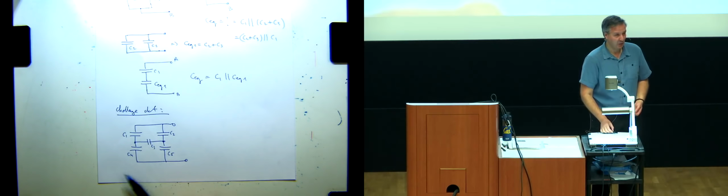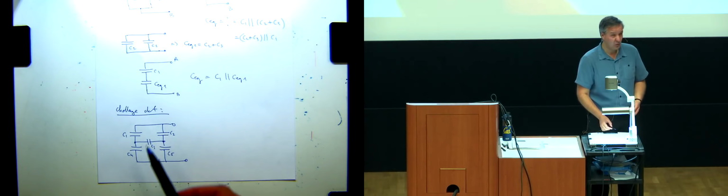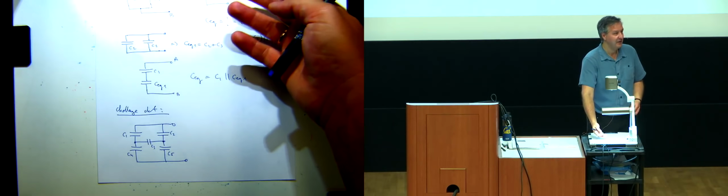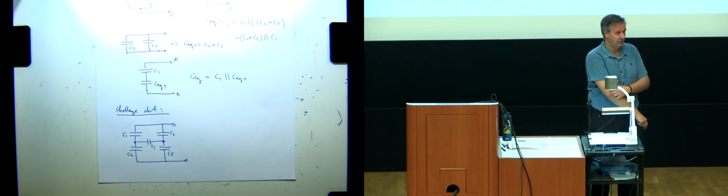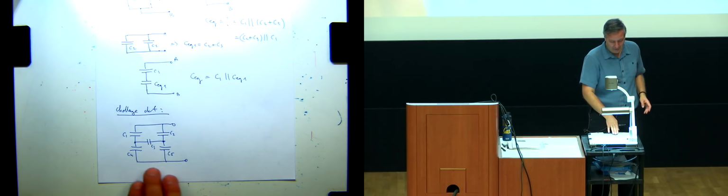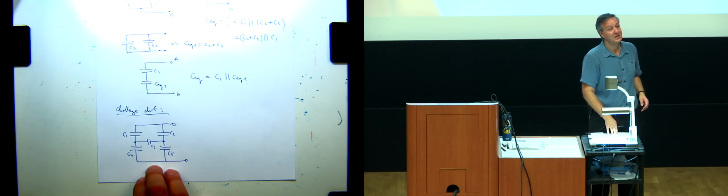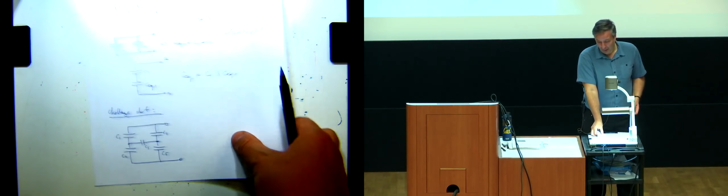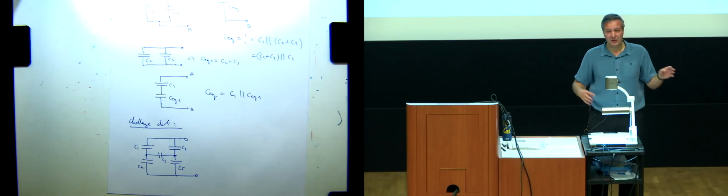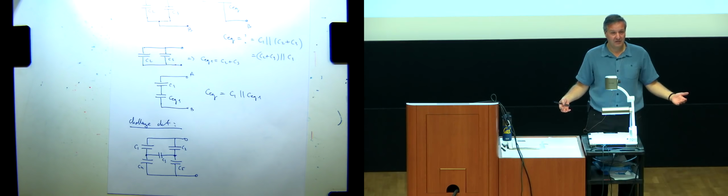These are classical bridge circuits that trip you up. So for this one, you likely will have to apply I test, V test, or dV test, dt, and then solve it. And that's very doable. But you won't be able to just see what's in series and what's in parallel. So be careful, because sometimes you can rush in and make a mistake. Whenever you're confused about what's in series and what's in parallel, just use the I test, dV test, dt.